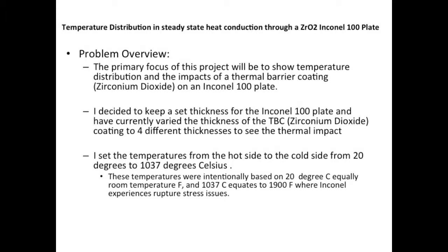I have also set the temperatures of the hot side and the cold side to 20 degrees Celsius and 1037 degrees Celsius. These numbers were chosen based on 20 degrees Celsius equaling room temperature, about 68 degrees Fahrenheit, and the 1037 degrees Celsius equaling 1900 degrees Fahrenheit, which Inconel experiences rupture stresses at.